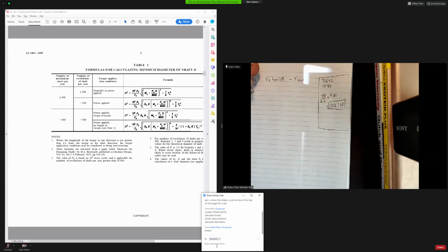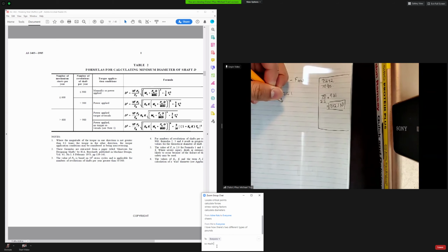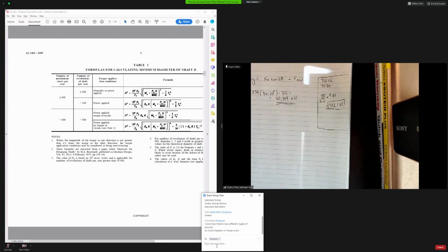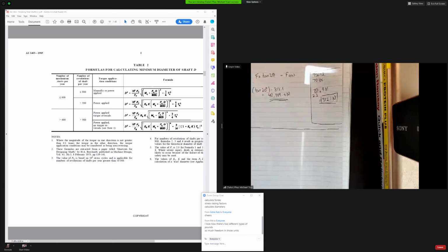So 111,854 tan 20 in degrees, obviously, minus 312.1 equals. I've got 4399.4 newtons. Cool. So that's our forces at that gear.